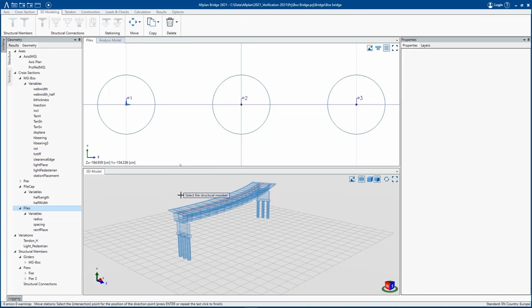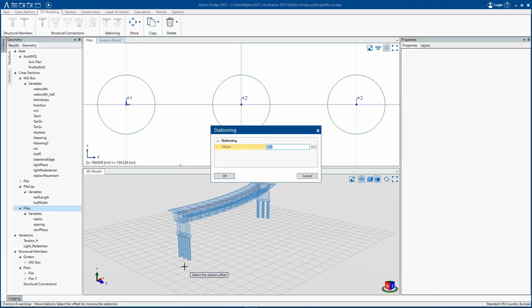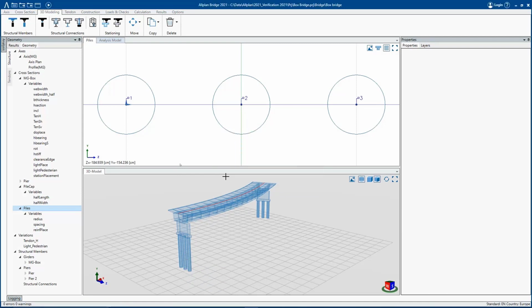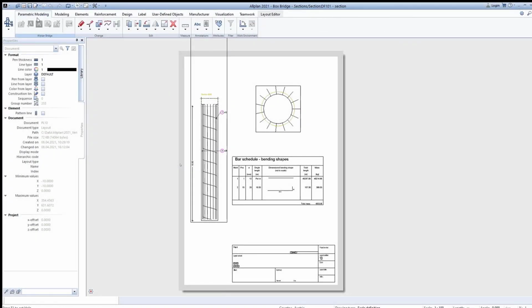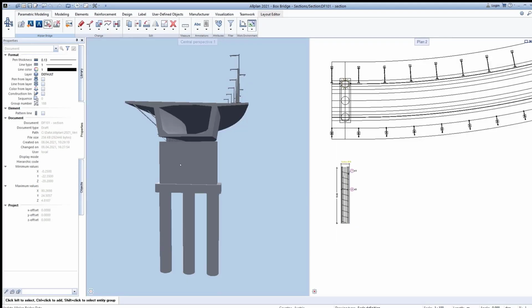And what if I make some changes? Like I said, parametrically, everything is updated. So let's change our pile height. I will add 5 meters. So it will be 15 meters. I will just calculate it here. This was the previous drawing. I will just now go here and update my model.